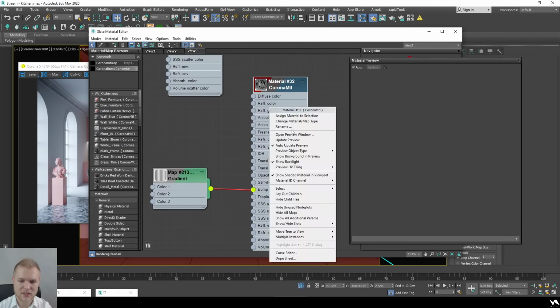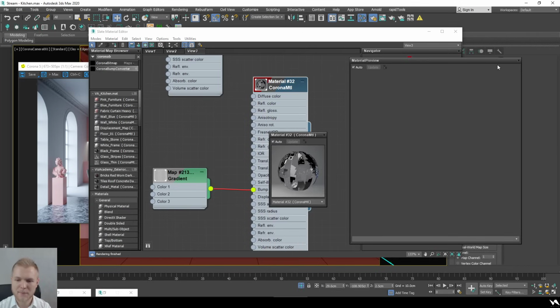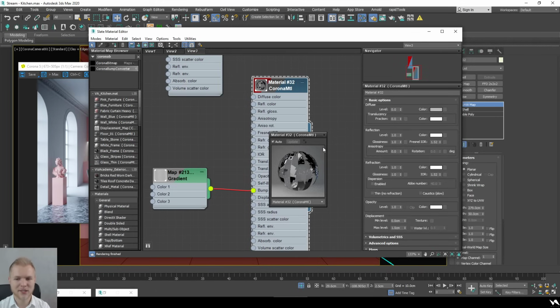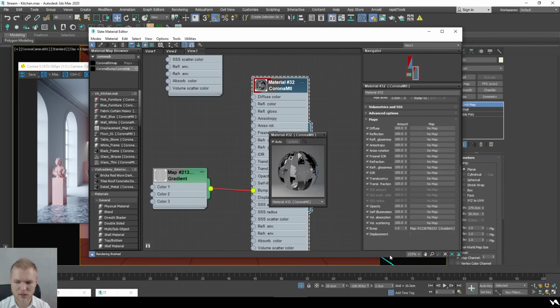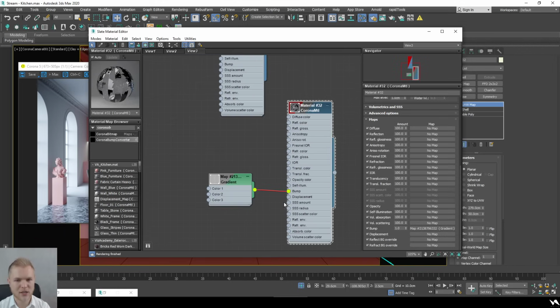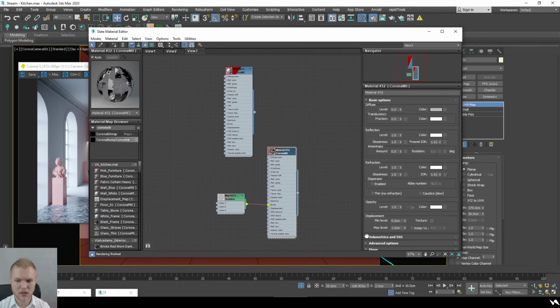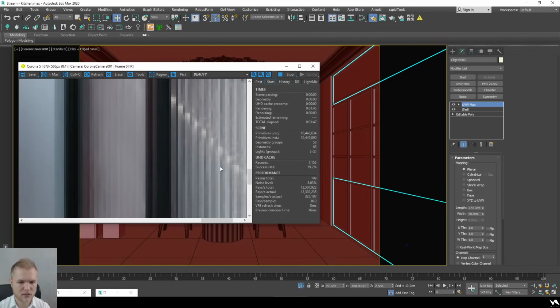As you can see, it's basically the same premise, but the glass material reacts a little bit differently to it. So all we need to do is make sure that the bump is set to a little bit higher value than 0.1. So 1 is going to be enough most of the time, but you don't have to stick to it. Now this is not a thin glass, remember, that's why we added this thickness. So it's actually going to create this effect.